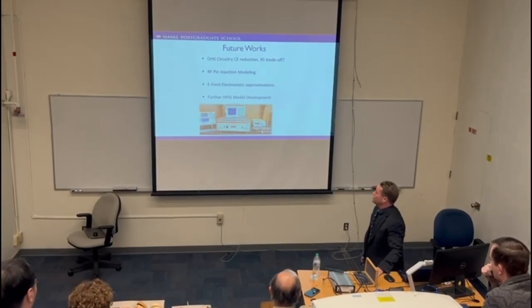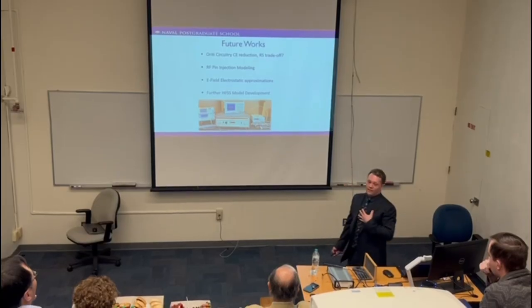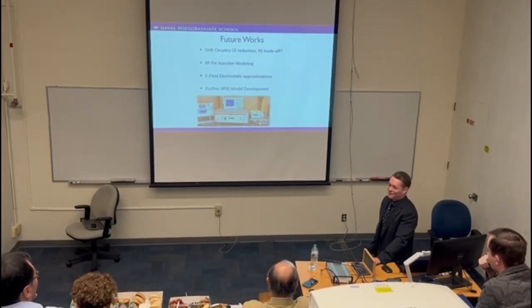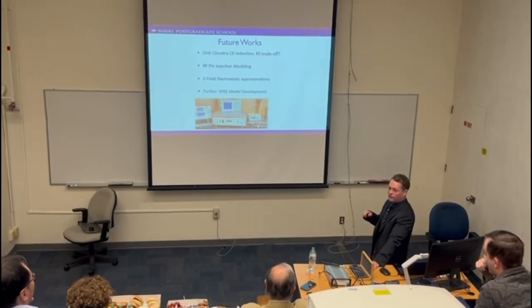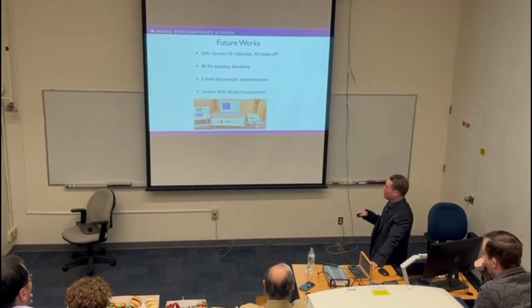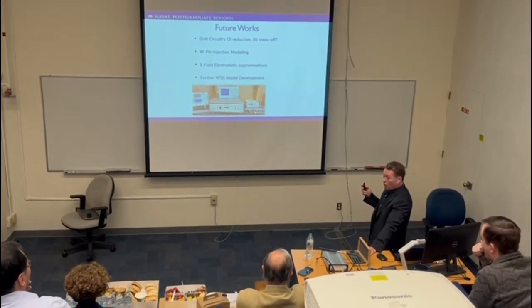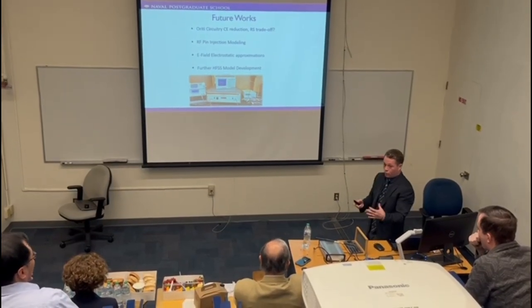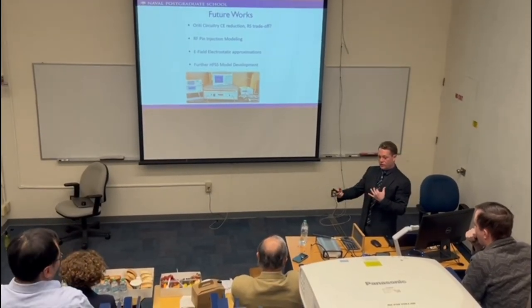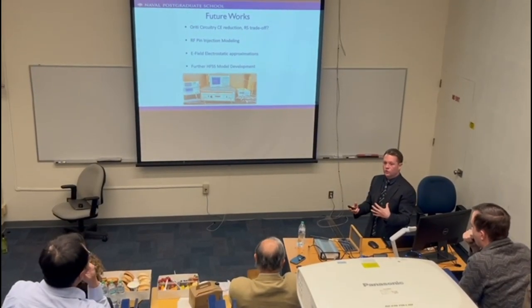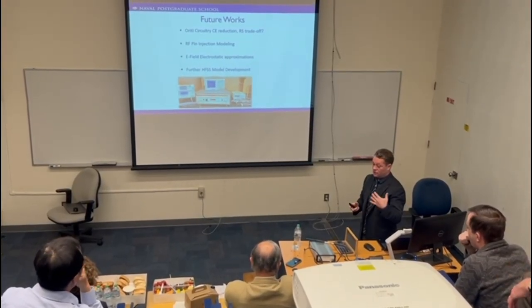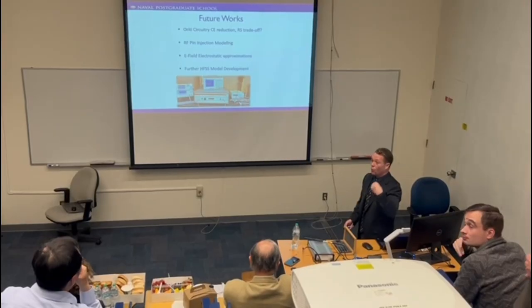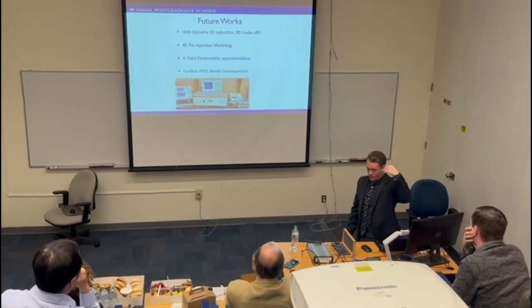Okay, so future works. I keep going back to this. I know Professor Reedy is very busy, but I just think it would be so cool, in the conducted emission testing that she's doing, to show that in order to improve some of the conducted emissions, she's increasing or decreasing inductance in circuits. She's balancing circuits. There are all these different elements being added to the circuit to cut down on conducted EMI. What's the trade-off on the radiated side?